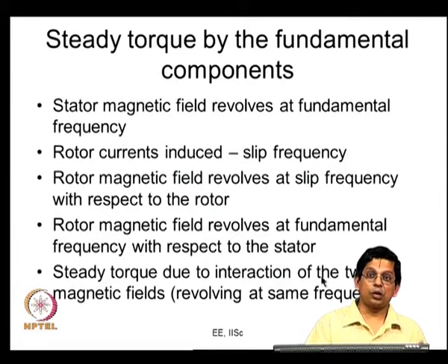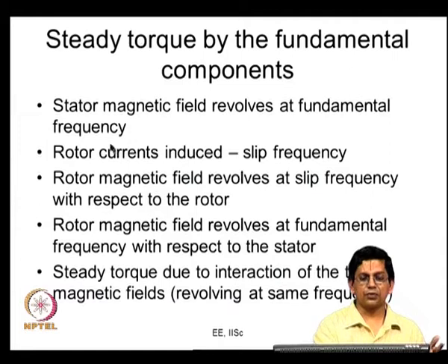Whereas this is not true with a synchronous machine. A synchronous machine, what happens? The stator side is very similar to an induction motor. It is a 3-phase winding, you may be applying 3-phase voltages, so it produces a revolving magnetic field at synchronous frequency, but how about the rotor? The rotor is at standstill. So, if you excite DC through that, it is not producing a revolving magnetic field at synchronous speed, therefore, it cannot start.